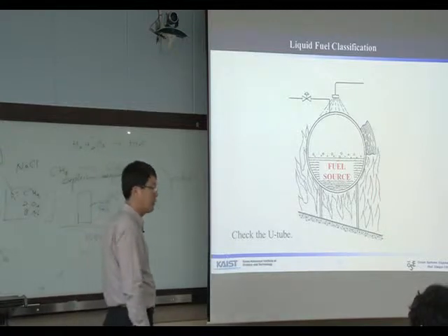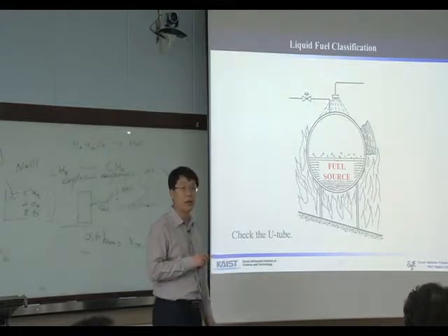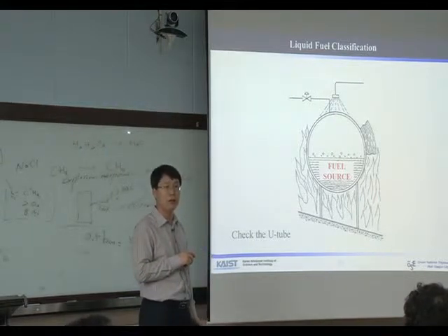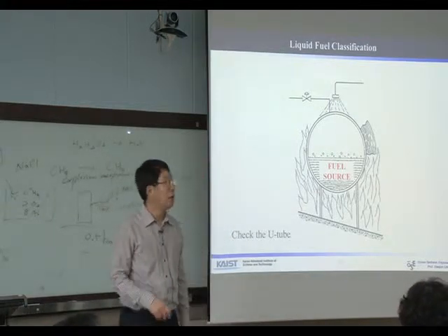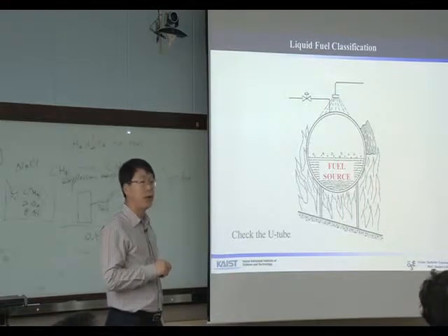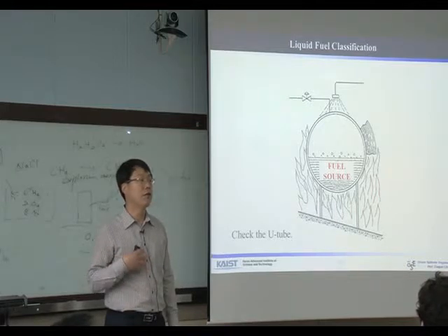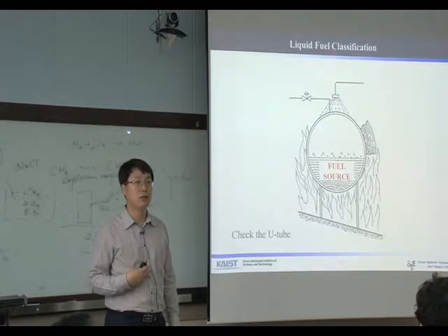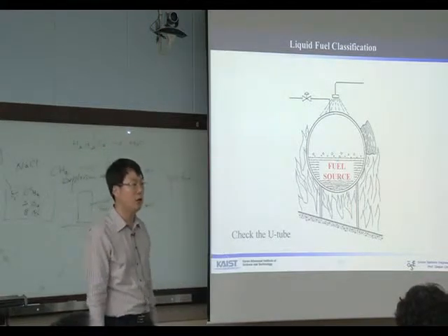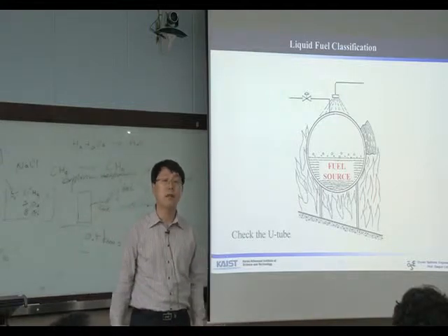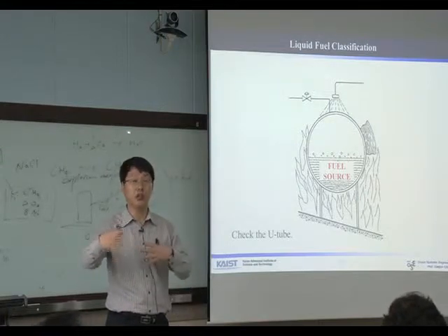But the more important role of this spray, this is the deluge, pouring water all over the equipment. The material strength of steel decreases rapidly with temperature. So we usually give a factor of 3 for structural safety design. We have some margin